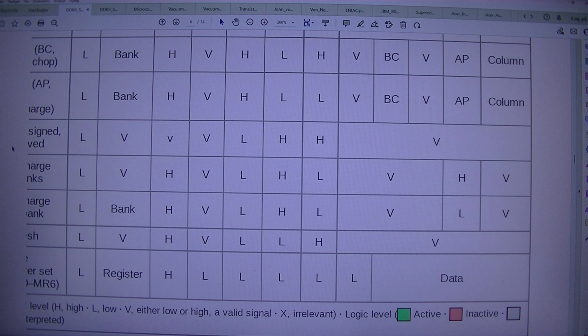Design considerations. The DDR4 team at Micron Technology identified some key points for IC and PCB design. IC design: VrefDQ calibration. DDR4 requires that VrefDQ calibration be performed by the controller.